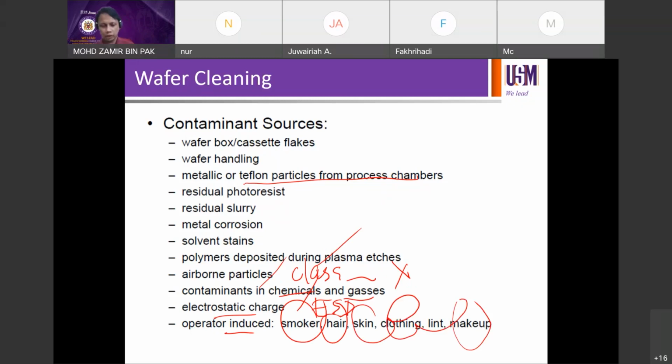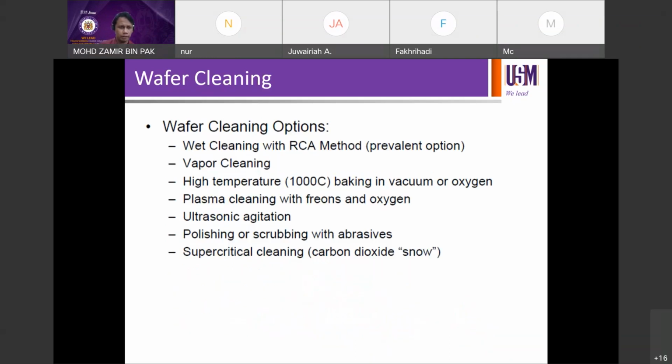So that's the whole idea of wearing your PPE, personal protective equipment, so that you are protecting the wafers against you, instead of protecting you from the wafers, right? We are protecting the devices and the products against us, because we are the ones who cause contamination, right?